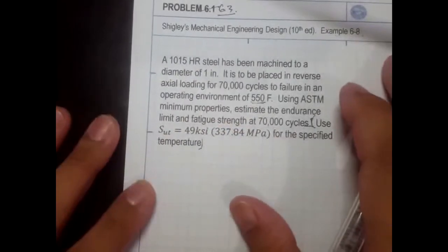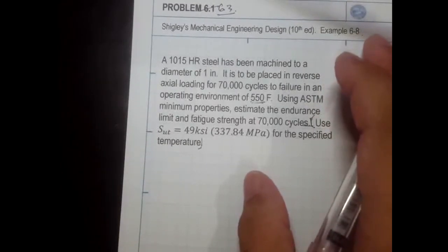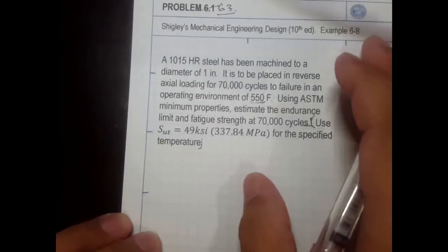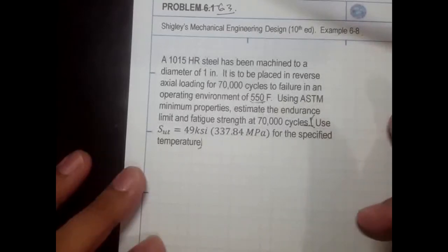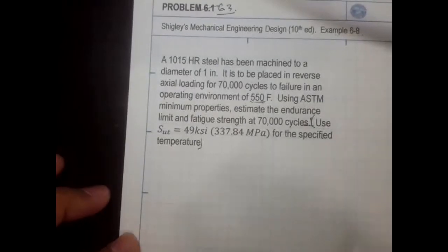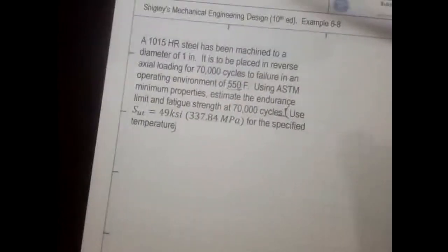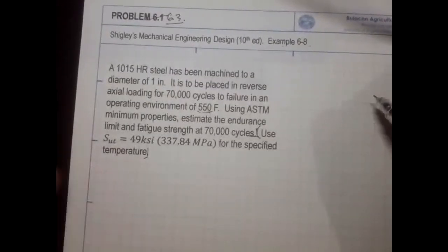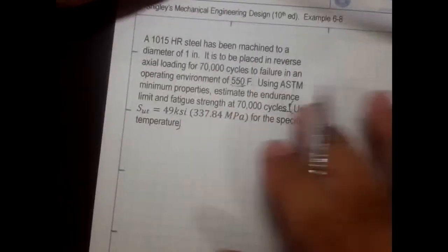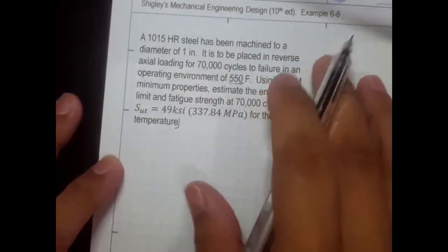Now, just a couple of notes here is that once the material is subjected to higher temperature, there's actually a decrease in the strength. So let's say we have a yield strength of 250 megapascal for static tensile loading, if it is subjected to higher temperature, then that's not going to be 250 megapascals anymore. Right, so that's just a side note.